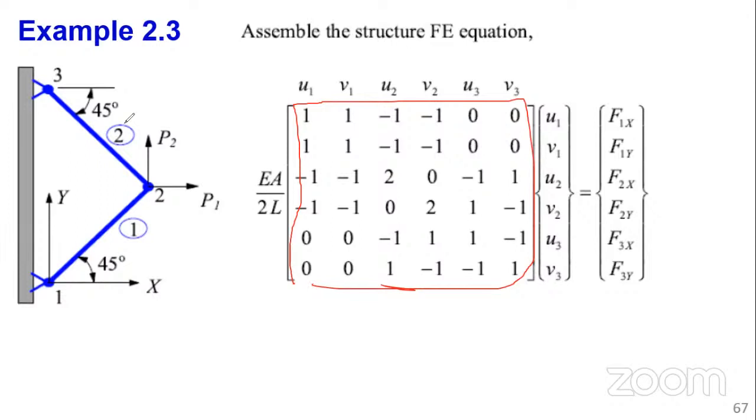Okay. Now, once you reach this stage, you have the global finite element equation. Nothing much now remains here. Just follow the procedures that you are following. Bring in the boundary conditions, reduce your equations, solve for the unknowns, nodal unknowns, and any other derived quantity that is required. So what do we know so far about the boundary condition? We want to define the boundary value problem.